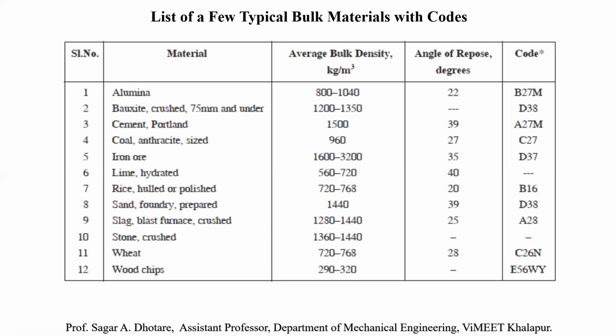It normally works on the angle of repose of 22 degrees, and it has a material code B27M. Similarly you can identify the different codes for different materials.